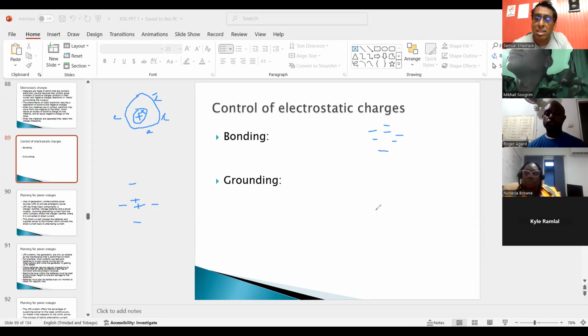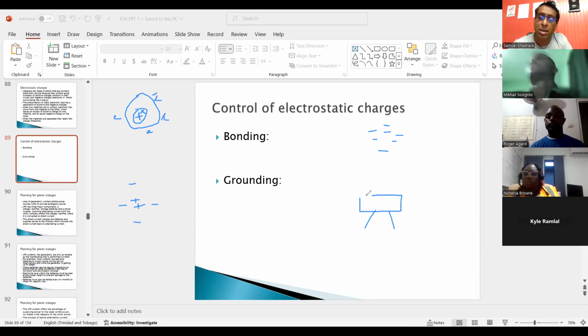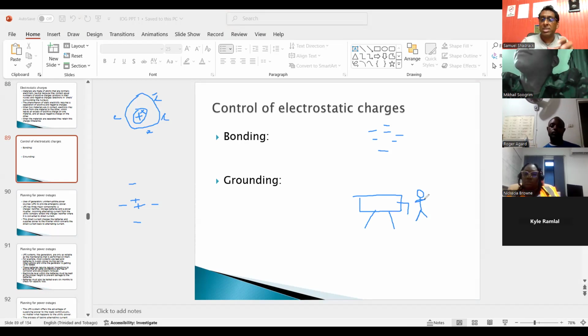That is kind of hazardous if you think about those of us in the companies, if you have a diesel storage tank, right? And workers are coming to this diesel storage tank to withdraw diesel, of course, right? But the workers are standing next to the tank, they're rubbing up on the tank. That could actually result in static electricity building up on their coverall. And they say just a spark, if this is diesel, could cause a fire.